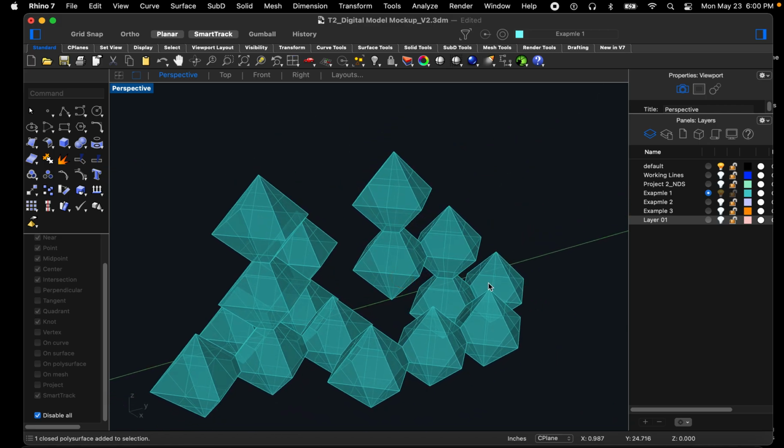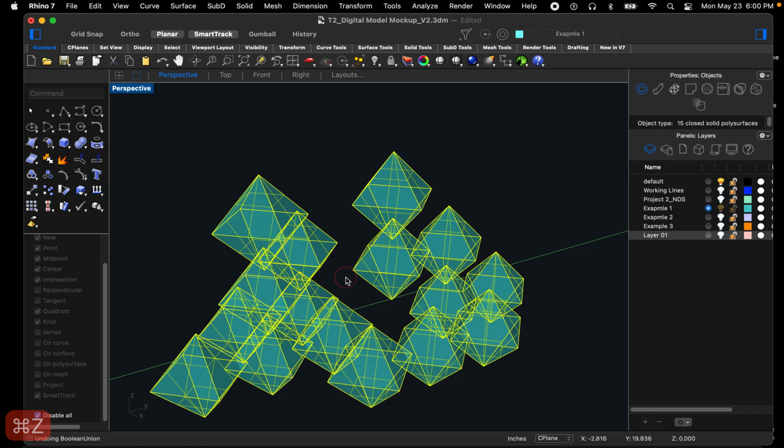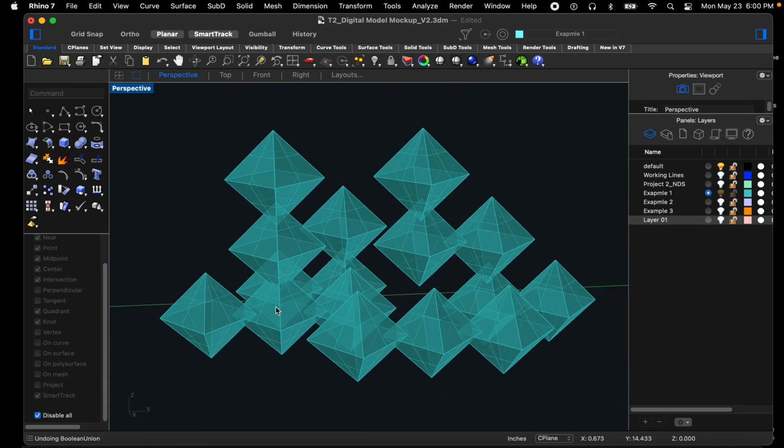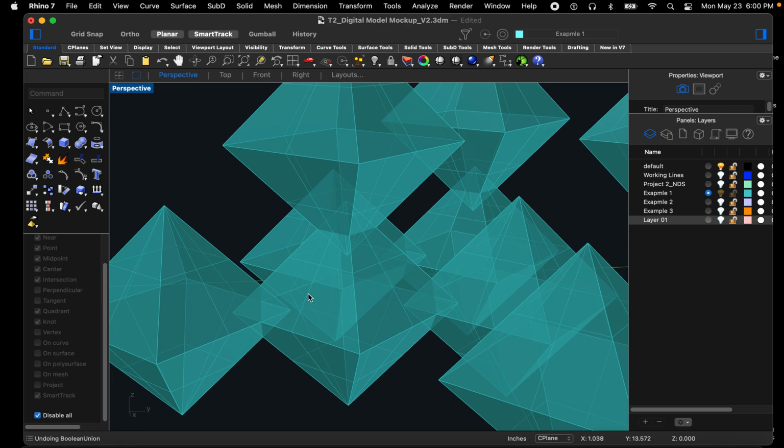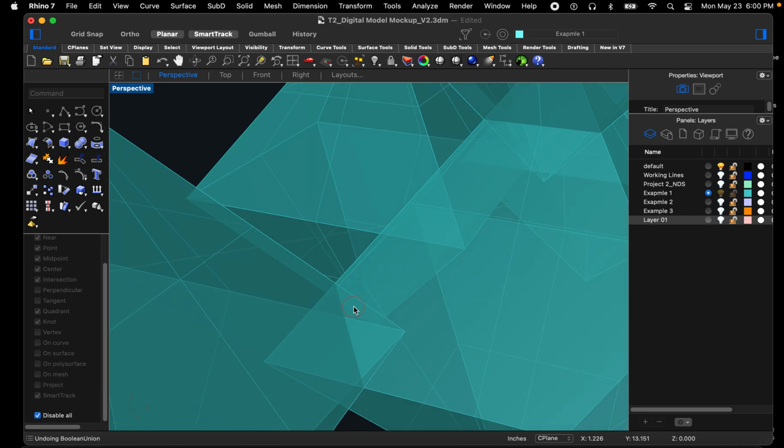Now, the reason this is important, if I just step back, this overlapping geometry is potentially a major issue. Okay, I know several of our 3D printers in the RPC, this would be a major issue. I know 1 or 2 3D printers that it's not an issue, but the basic principle, the rule of thumb, is that this sort of condition, this overlapping geometry, is always going to potentially be an issue.